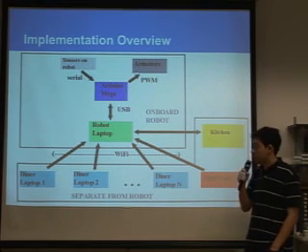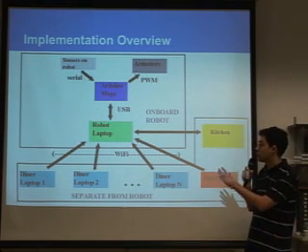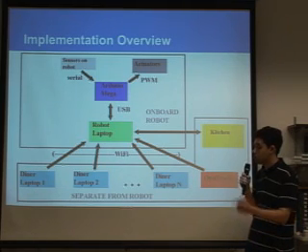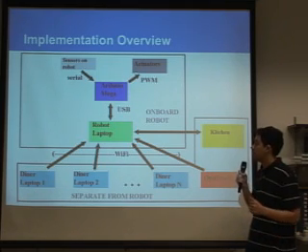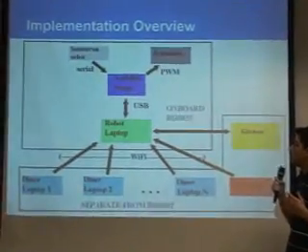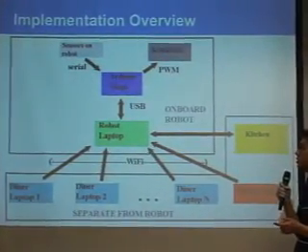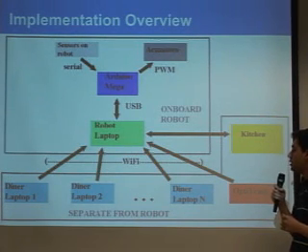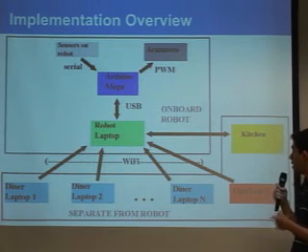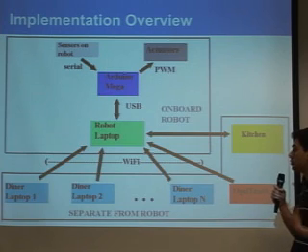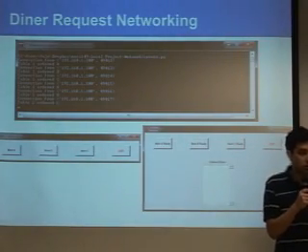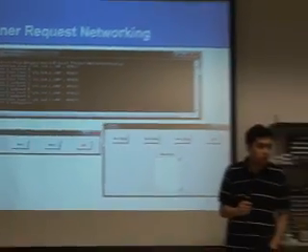So just to show you the general architecture, on the robot we're going to put a laptop, and that's connected to an Arduino Mega. They communicate serially, and then the Arduino Mega is connected to the robot's actuators and sensors. We have the diner laptops, OptiTrack, and the kitchen laptop communicating with the robot laptop over Wi-Fi. So Yale's going to talk about the networking.